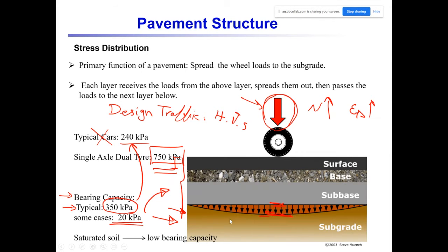Also, as I mentioned, the strength of the material matters, because soil is a multi-phase mixture. It's a mix of solid phase, water phase, and air phase. So we know that the amount of water in the soil will affect its mechanical behavior and the strength of the material. The most susceptible and vulnerable case generally is when the soil is fully saturated and the drainage condition is undrained. In that case, generally the strength of the subgrade will reduce.